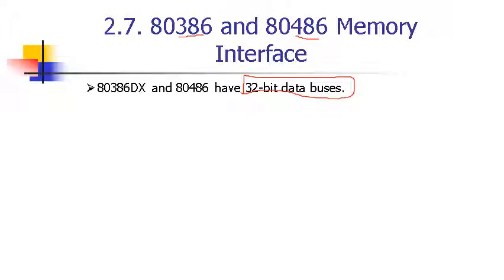So to get at a clock cycle 32 bits out of your memory, you have to arrange your memory into 4 different banks. Each memory location is a byte. So at a clock edge you will get 4 bytes, one from each of these 4 banks, so you can get 32 bits at a time.